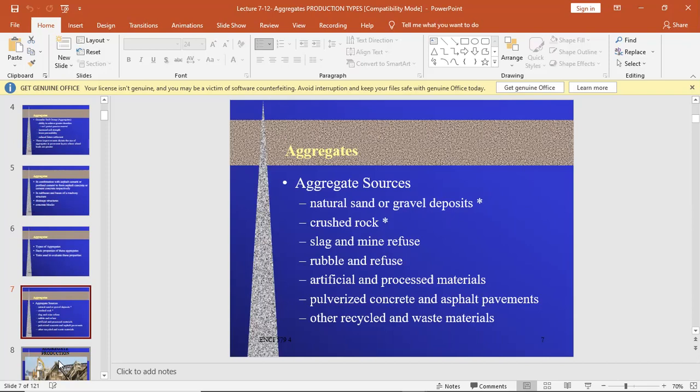More than 15%, then you have to be very specific. So we don't go into the juggle of recycling aggregate. You are not going to the maximum; you are going to get 15%. 85% you still have to get from natural resources, and even this has to be allowed by the consultant.